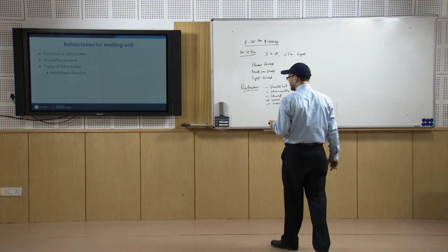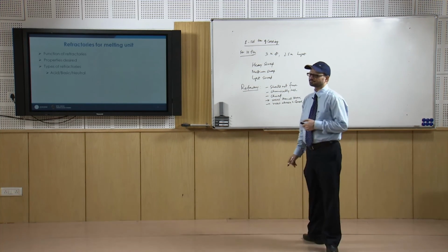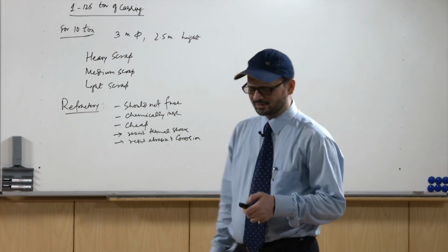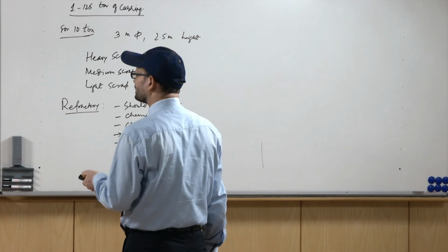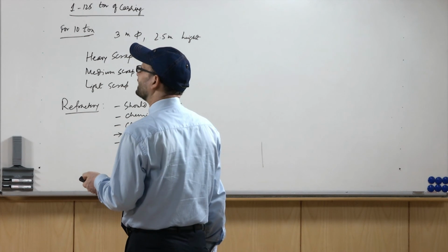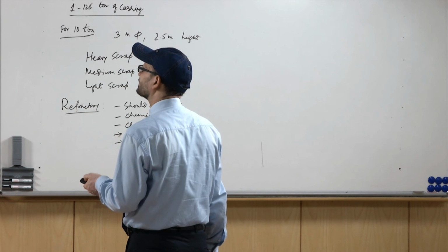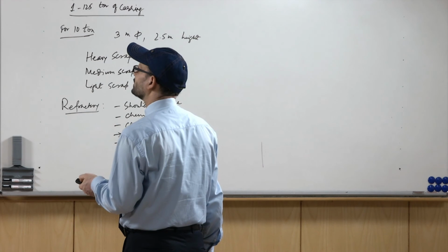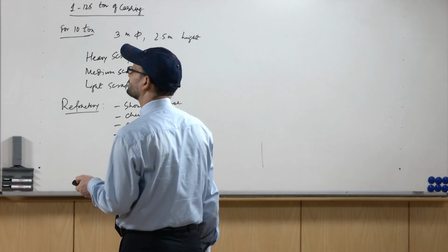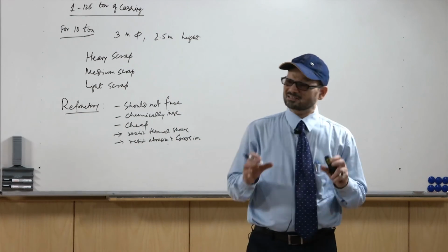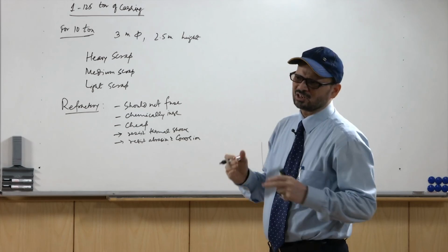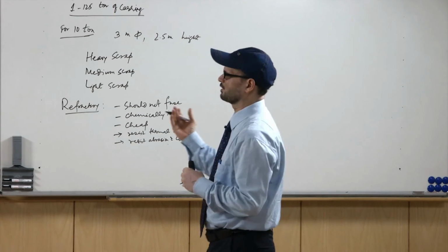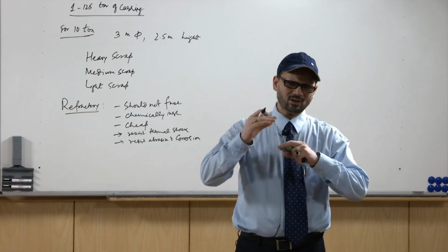In acidic, basically they do not react with the acid slags. Normally they are silica based, so that is acidic. Then you have basic, which are normally based on dolomite or bauxite; these, magnesite, are used as the basic refractories and they have better qualities.